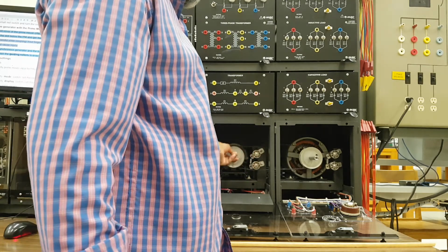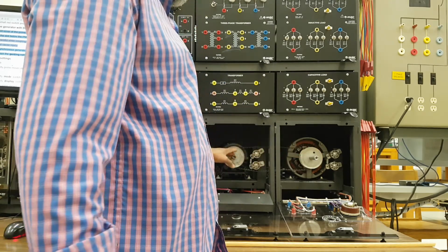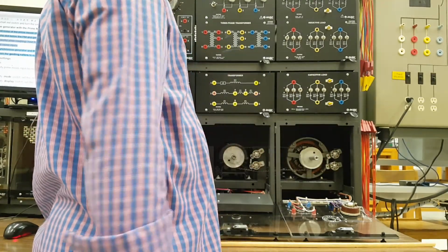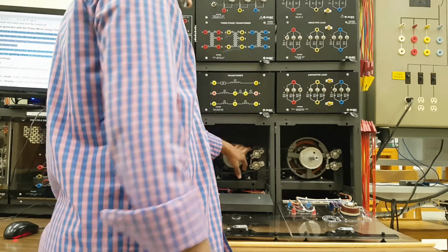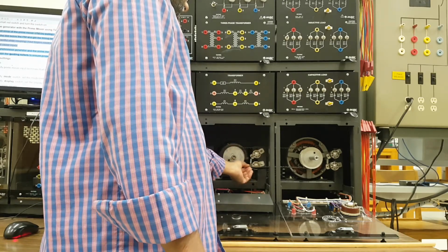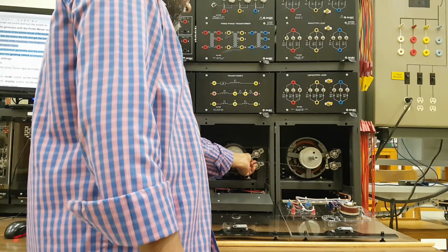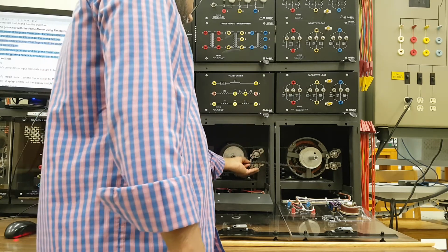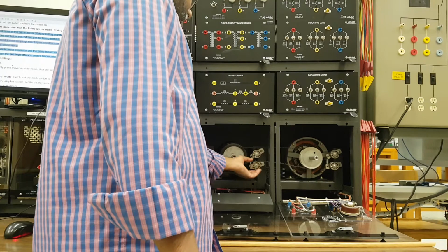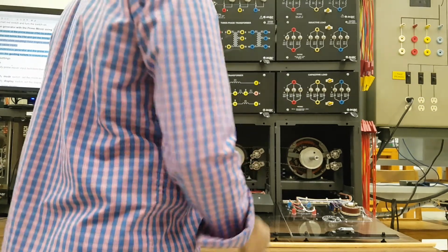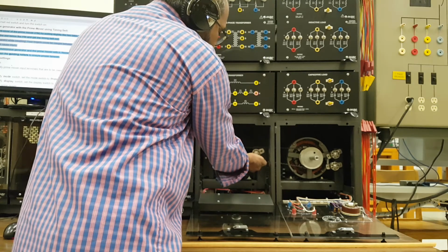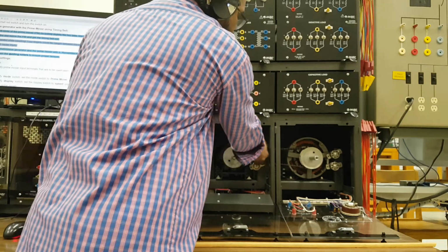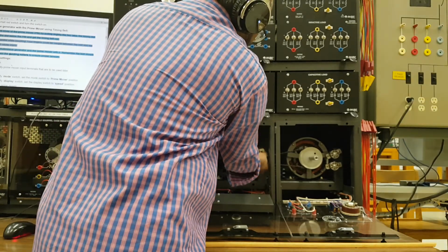Now you can see this is a little loose. If you leave it like this, what happens? The speed of this one and the speed of this one may not be the same, because there is a chance of slipping. So to make sure both speeds are the same, we have to create tension in the belt. The first one is easy. I put this one on top of the bottom roller, and the top roller I lift with my fingers. At the same time, I pull down the timing belt, and at some point it will go inside.